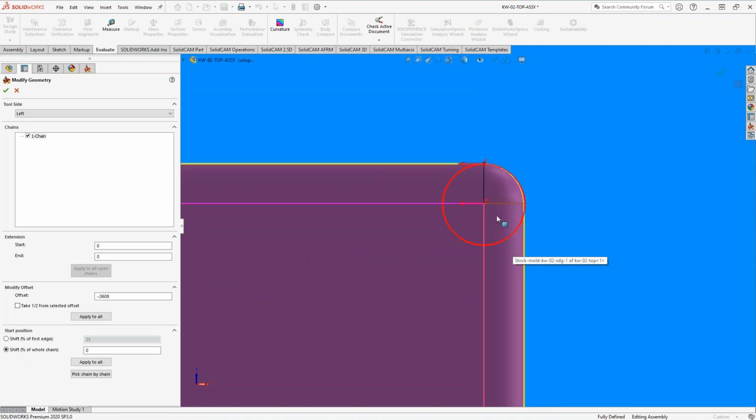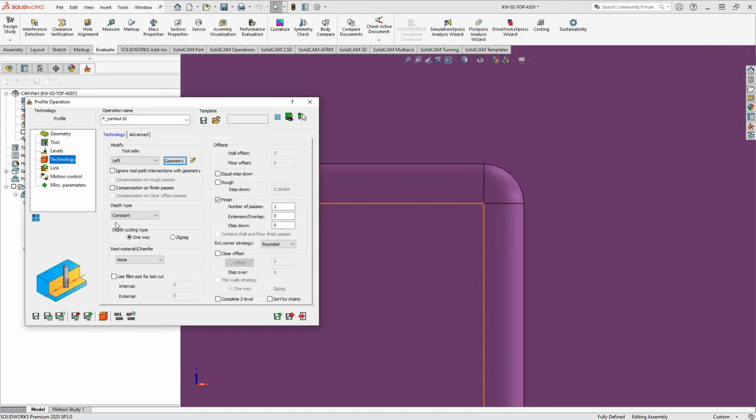My tool is larger than that corner radius, but we know from my radius that if I step up by that much, I'm actually right on the wall there. So I'm going to form that corner exactly as intended, at least in that edge and that edge. And this corner is going to be the 1/8 size of the tool. Hopefully that's making sense. So save and calculate.